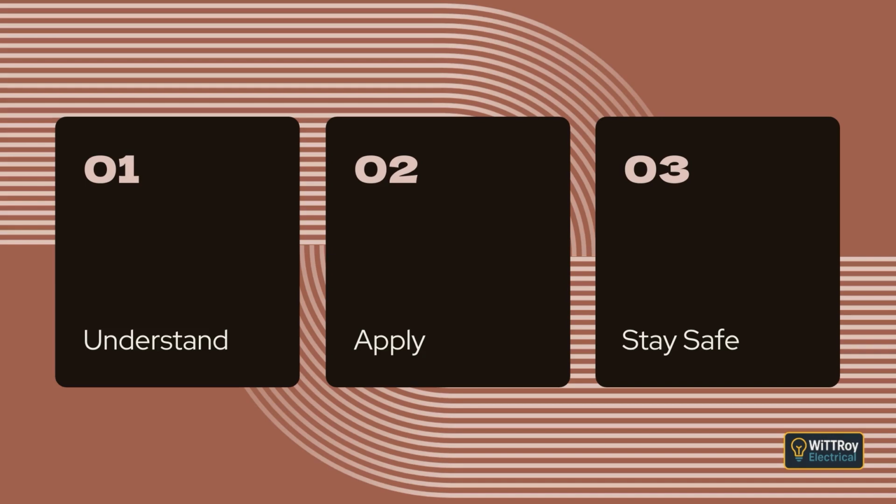There are some exceptions. For example, medical treatment areas used for home dialysis follow the special rules in AS/NZS 3003. Some alterations or repairs may not require RCD protection if they meet the conditions in Clause 2.6.3.4. A socket outlet for a fixed cooking appliance may not need an RCD if it is in a location not normally accessed by the general public and is clearly marked for its restricted purpose. This clause aims to make sure that places where people live and move around most often have strong shock protection.